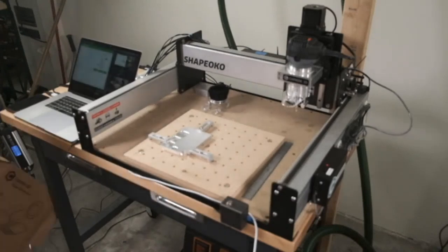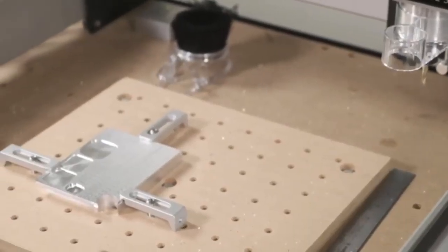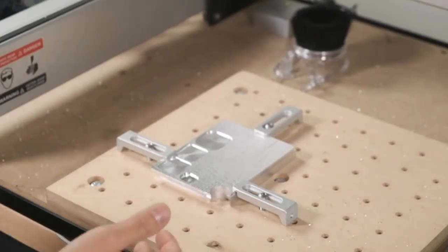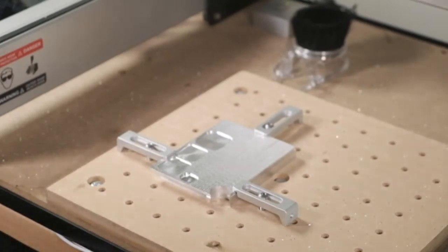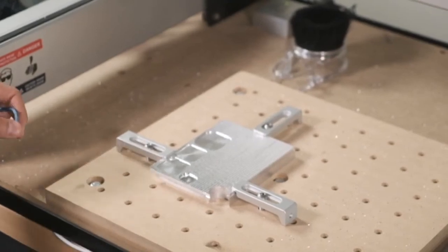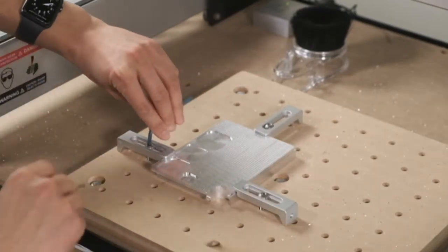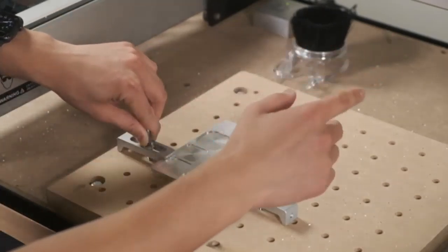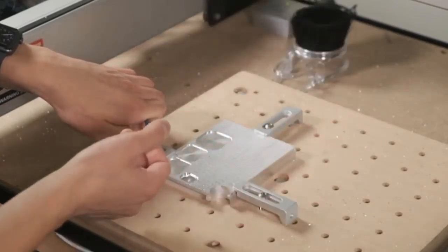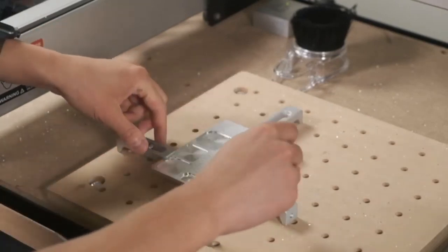Okay, so let's talk about what just happened. Let me zoom in, let me take the workpiece off. So one of the other questions that people asked was, what should a good cut sound like? And you're looking for a nice consistent tone without any sort of macro scale issues. If you have chatter or vibrations on the frequency or intensity of a helicopter hovering over your house, that repetitive thumping, or like a machine gun, vibration on that scale is low frequency enough that it indicates that your machine itself, the router, is vibrating, rather than a high-pitched screeching or grinding, which would be happening more at the end mill. But either way, the tone of the cut should be consistent all the way throughout.